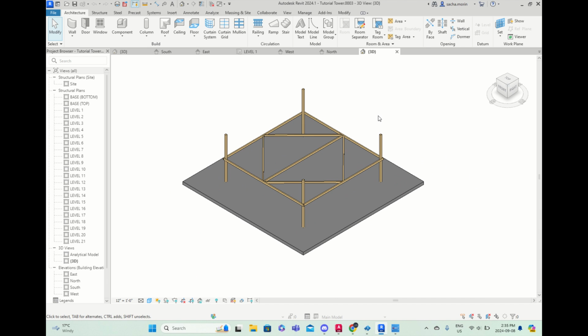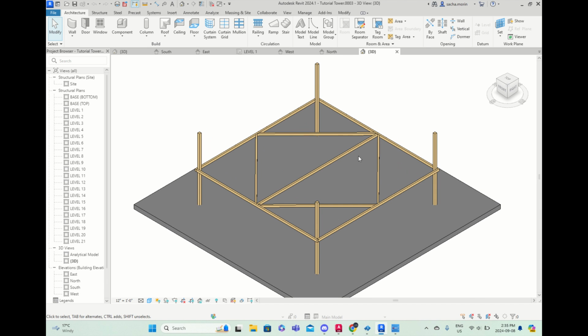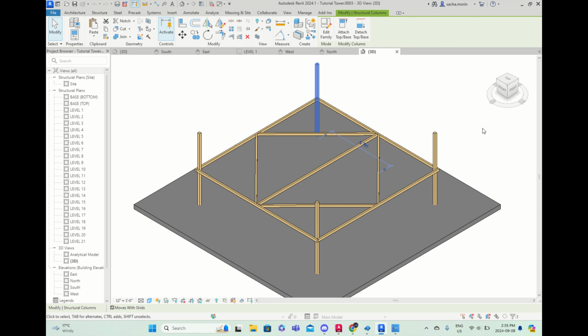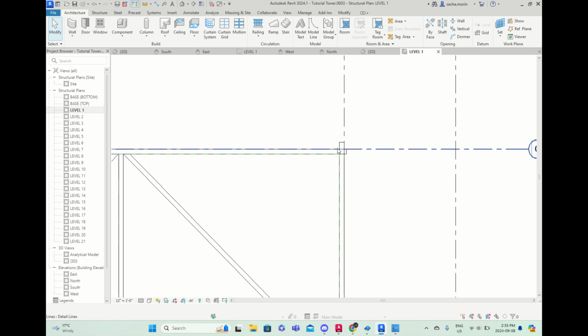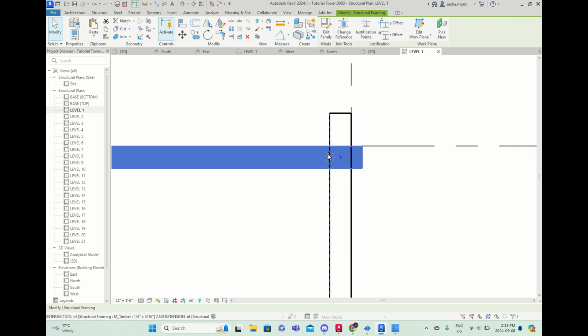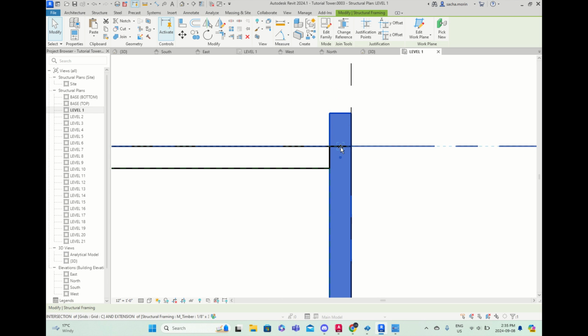So if I wanted to take this floor plan and copy paste it into the current model that I have, I would first have to delete all of the things that aren't the floor plan. So I'll delete the columns, base plates, everything. Granted, deleting the columns messes with the justifications of the floors, so let's fix that really quick. It's nothing terrible, nothing you have to be too concerned about.